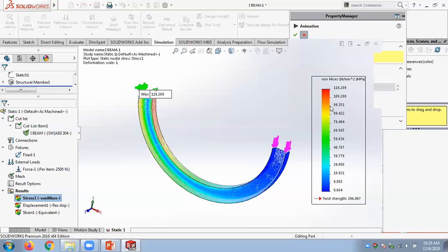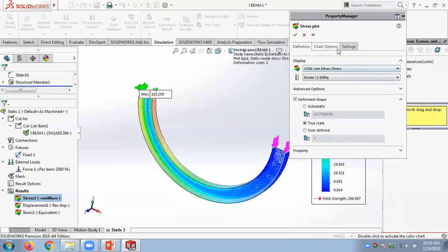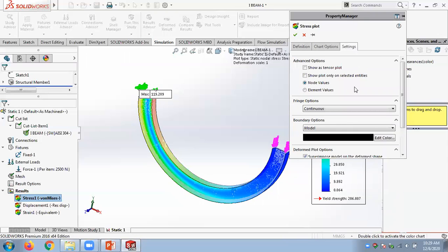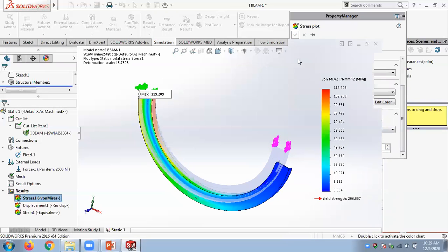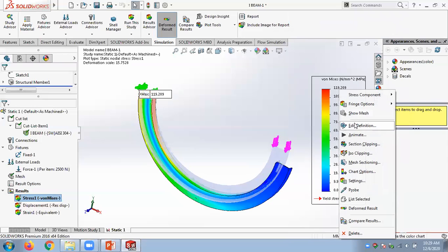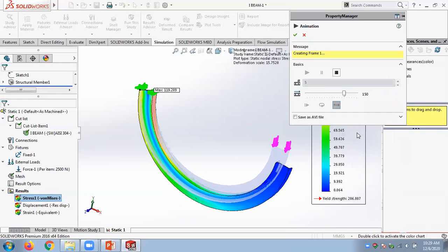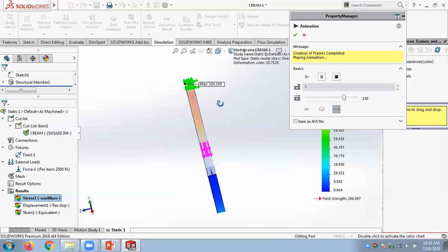That's why we need a higher scale. Otherwise, sometimes it's very difficult to see. So you can come here, go to superimposed model and have something like 0.4 and see both the shapes, original shape and the deformed shape. When you animate this, clearly I can see the changes. The changes are happening along this direction. It will not buckle.